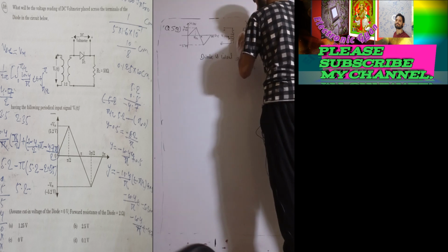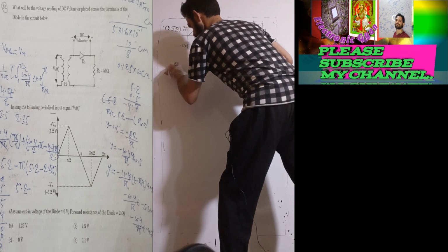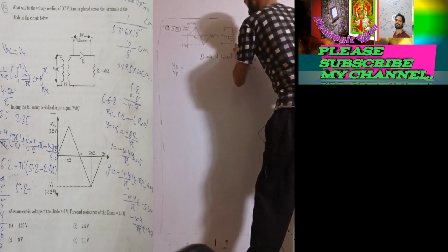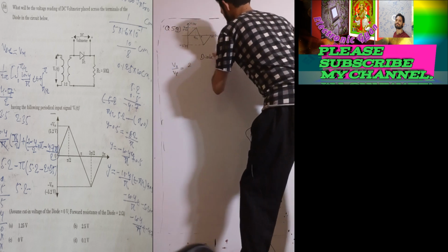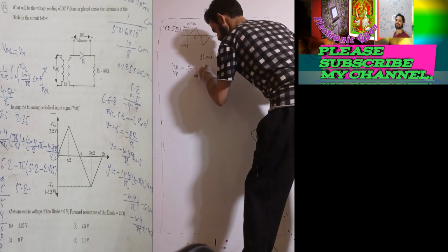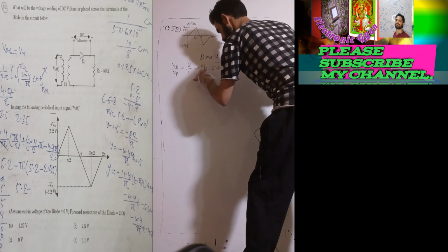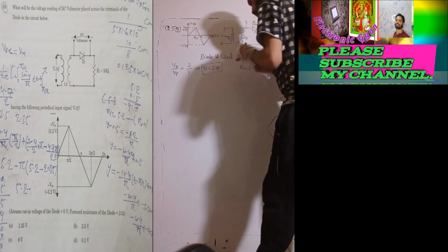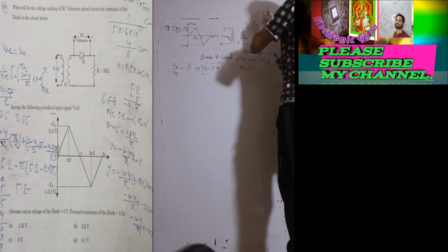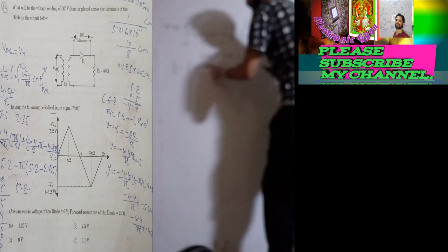Secondary voltage upon primary voltage is equal to the number of turns in secondary, 2, divided by 1, which implies that the secondary voltage is equal to 2 times the primary voltage. It is a step up transformer.